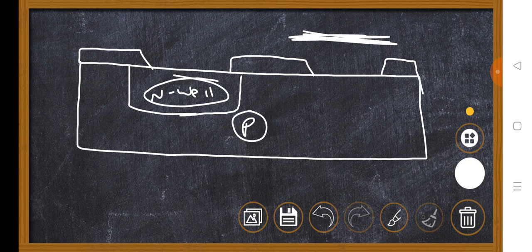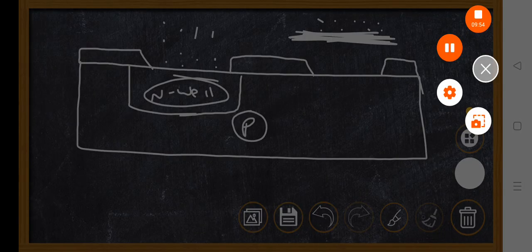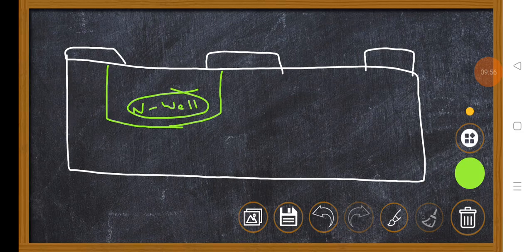Is it clear? That means after covering with a photo mask, if you expose with n-type impurities here, here also the n-type impurity will be there, but it won't fall into the substrate. Why? Because it is masked. Is it clear? Then your well is ready. Is it understood? Okay, now observe, the well is ready for you. Then what is the next step?